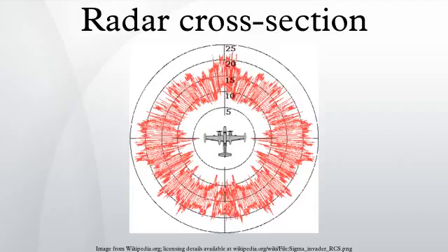Conversely, a square flat plate of area 1 m² will have an RCS of σ = 4πA²/λ², or 13,982 m² at 10 GHz if the radar is perpendicular to the flat surface. At off-normal incident angles, energy is reflected away from the receiver, reducing the RCS. Modern stealth aircraft are said to have an RCS comparable with small birds or large insects, though this varies widely depending on aircraft and radar.